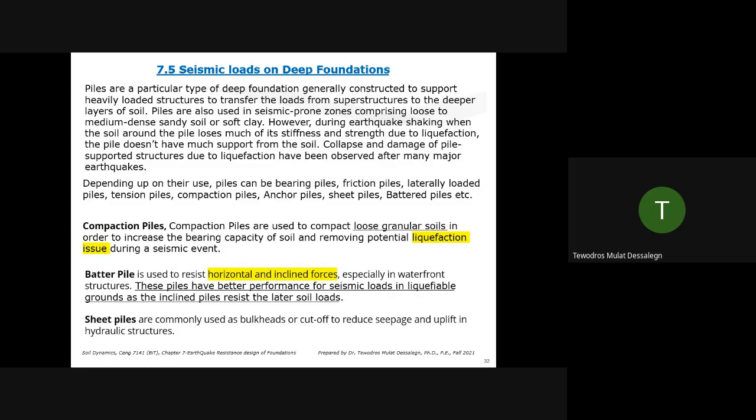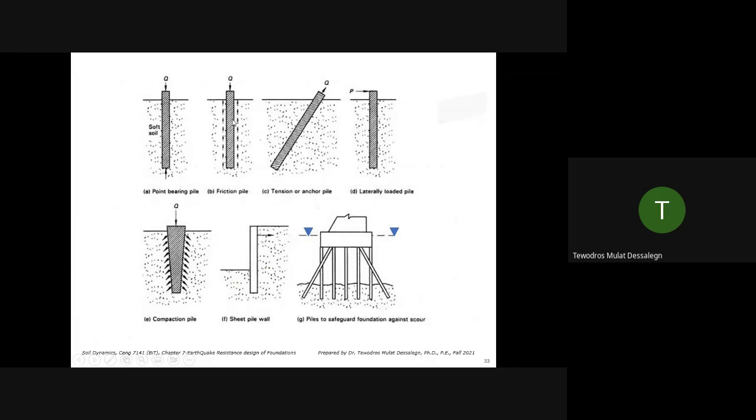And we can also use software for other time history analysis. For deep foundations, you can have multiple kinds, especially pile foundations with different configurations. You can have a pile in soft soil with point bearing, or a pile in dense soil credited for friction, or piles at an angle for different purposes. They can be loaded axially, but in the seismic case, you can have lateral load also.